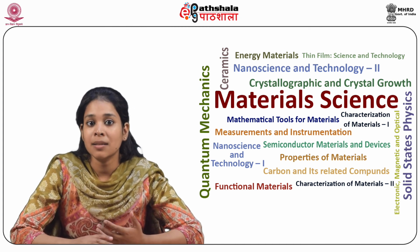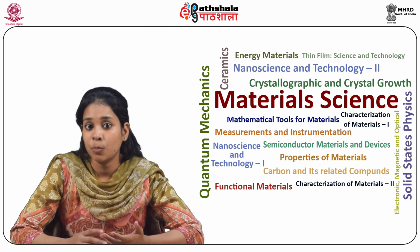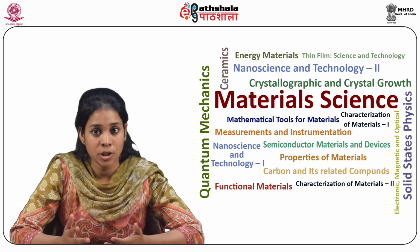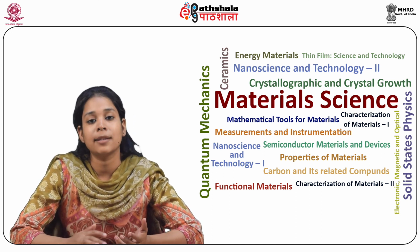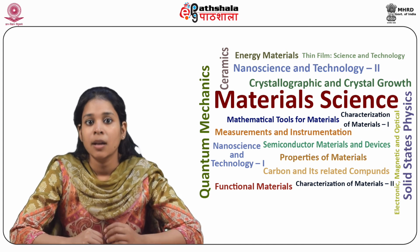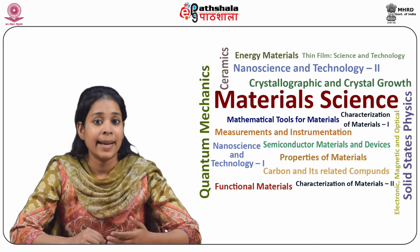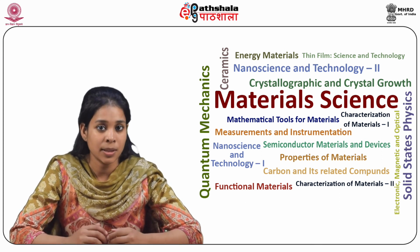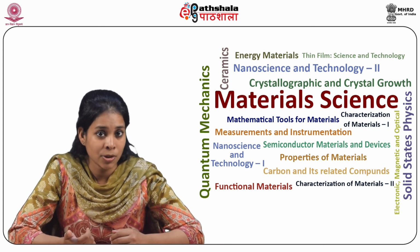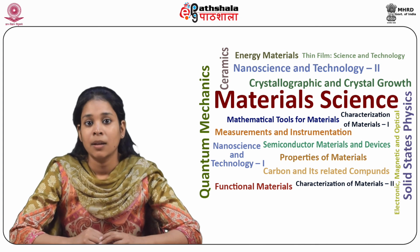So these are some advantages of liquid phase sintering. That is, it produces faster densification due to faster atomic diffusion and due to particle rearrangement. The grain size can be easily controlled. Next is, systems which are difficult or impossible to sinter by solid state sintering can be sintered using liquid phase sintering.